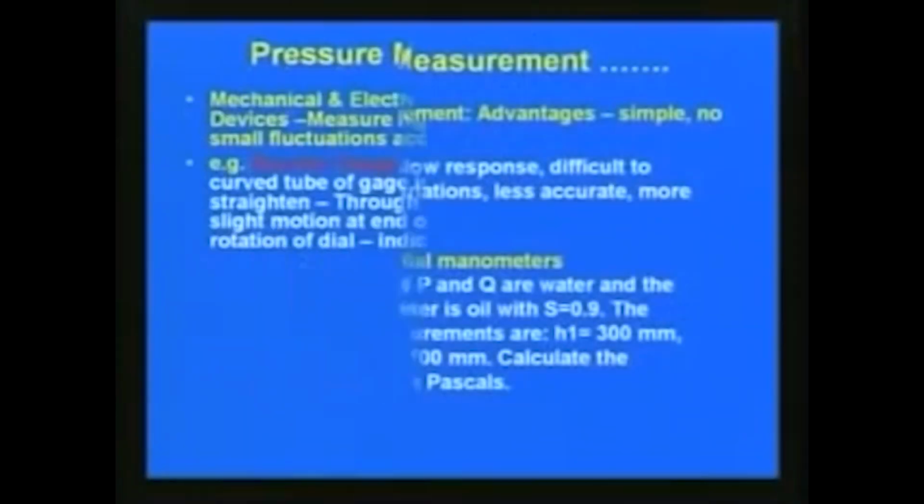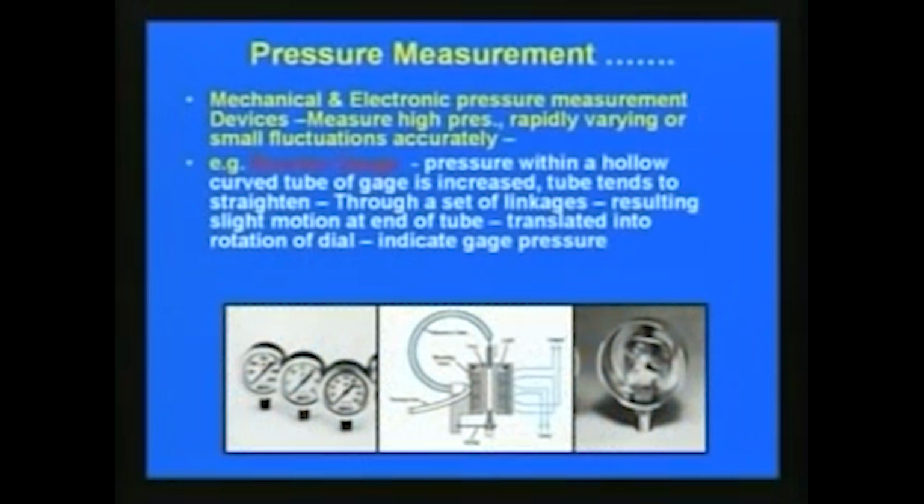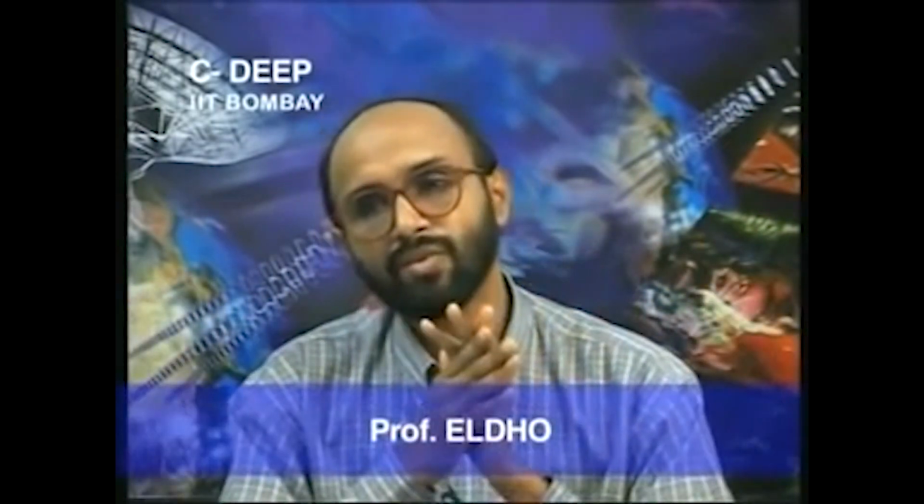So now we have seen how we measure pressure using a manometer, whether it is a simple manometer connecting to only one location, or a differential manometer connecting on both limbs of the U-tube manometer to find the pressure difference. And then we have seen the inclined or tilted type of manometer, and the advantages and disadvantages of manometer. As I mentioned earlier, pressure measurement using a manometer is cumbersome, since we have to measure the height and then use some equations to convert.